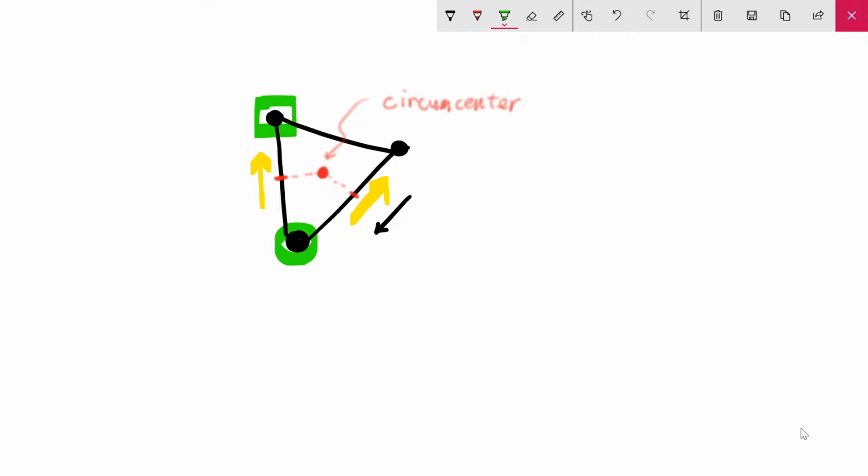So please try to evaluate this vector only once. This vector can be generated only once, and from the viewpoint of this center node, that should be regarded as positive or outgoing flux, and from the viewpoint of this vertex, that should be regarded as incoming, so contributing a negative value to the integrated divergence.